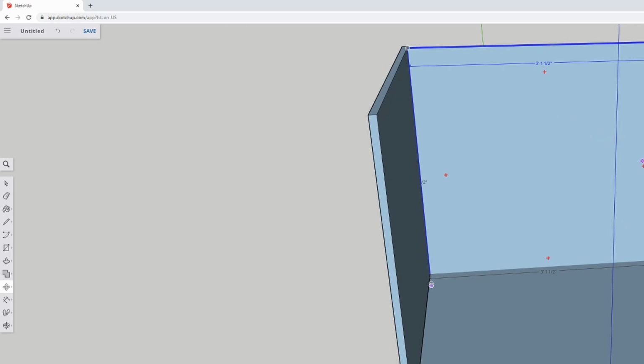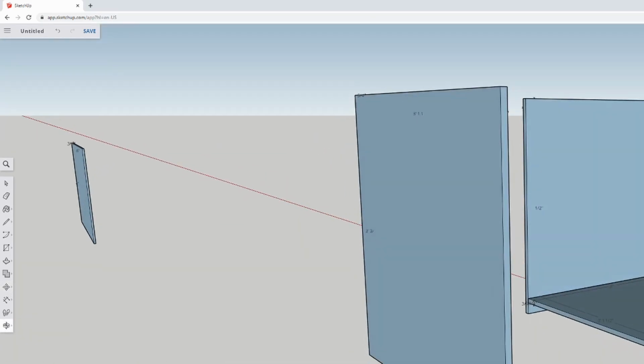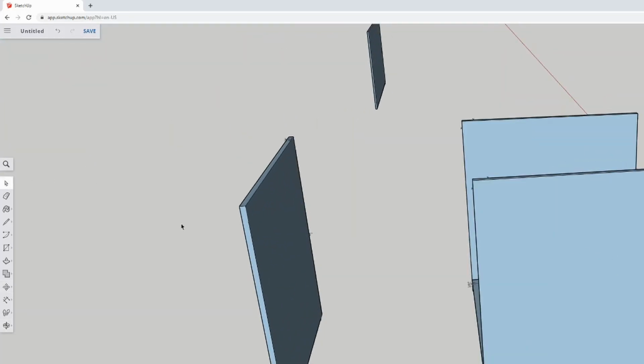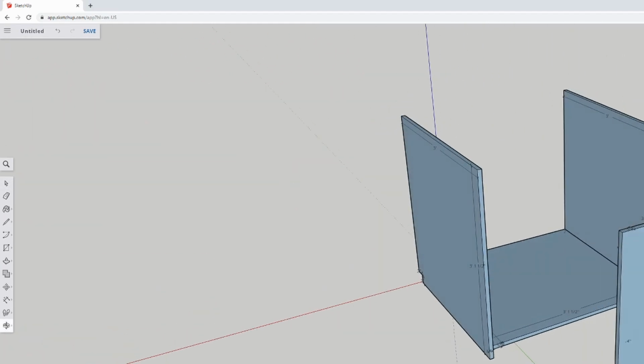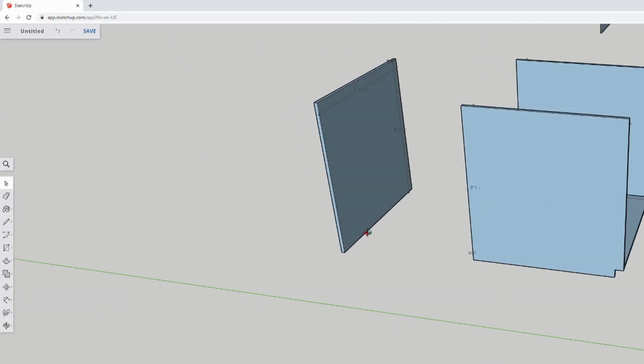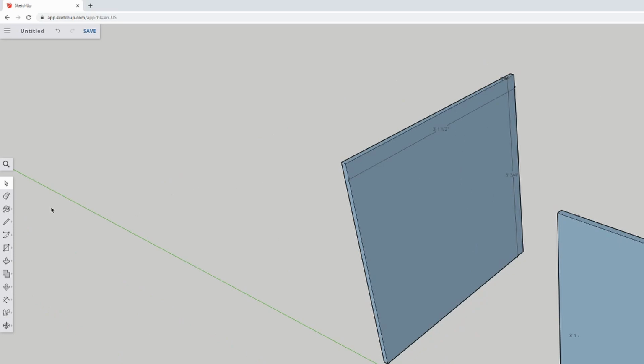So the back panel is offset by 3/4 of an inch because previously this piece was on the bottom. So what I will need to do is resize this. So let me move this back out of the way. Then I can select it, explode it, so that way I can resize it along a particular axis. Get it to where I can see my dimension lines. I apologize if I am moving around very quickly on this. Select my push-pull.